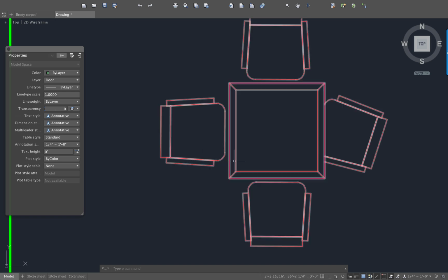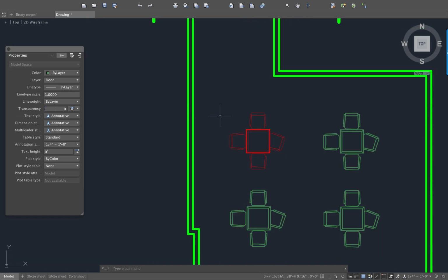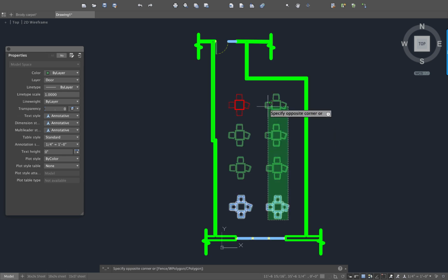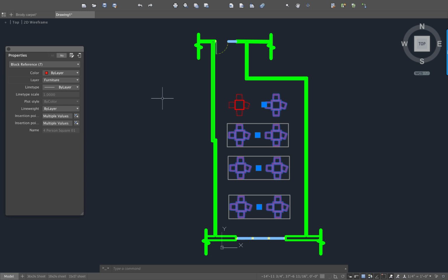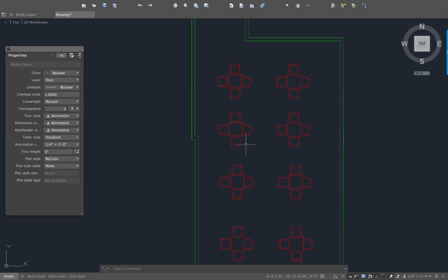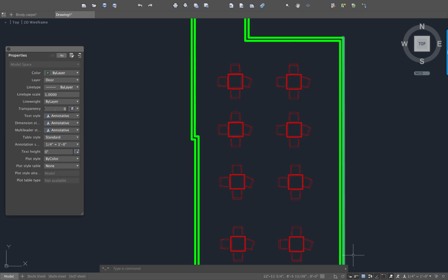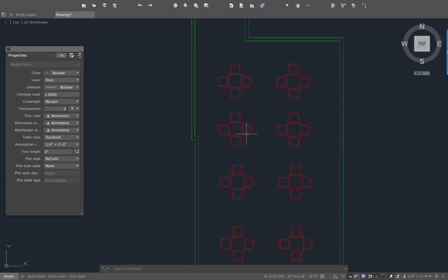And now you can get a little more definition out of those tables. Again, all of these objects want to be on that correct layer. I only changed one. Just resist the temptation to change the layer of the objects inside the block. It kind of causes everything to go haywire.